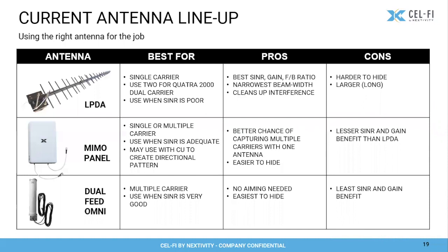The Omni is going to receive interference from all directions. What is good interference? What is bad interference? If you see, you know, SINR generally goes from, let's say, -10 dB to +30. Anything above 0 is okay. I like to see them above 5 dB. When you start getting into negative territory, -1, -2, -3 dB, just as I showed you on that earlier slide, you're starting to see less bars on your phone. Once it gets south of -6, -7, you can start having call drops, right?